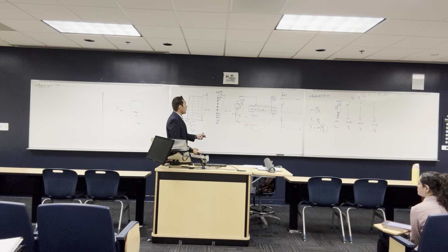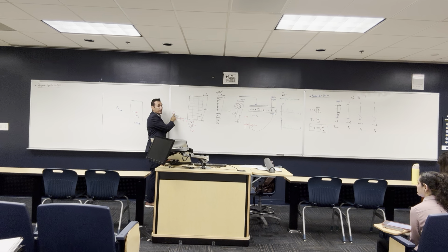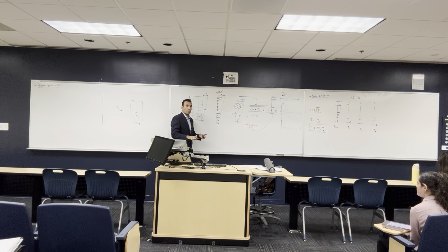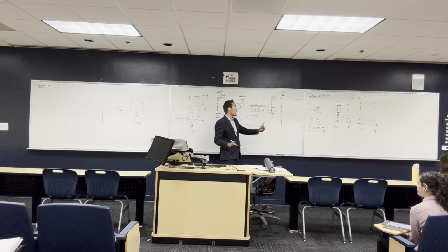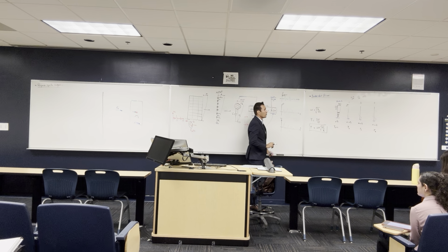But the thing is, I already know U, but I want to know how much force is shaking the base. What is this F base? F base is the mass multiplied by acceleration. But by the way, this acceleration is not the ground acceleration. It is the structure acceleration, how much acceleration this structure is moving. So we need to find the acceleration of the structure.